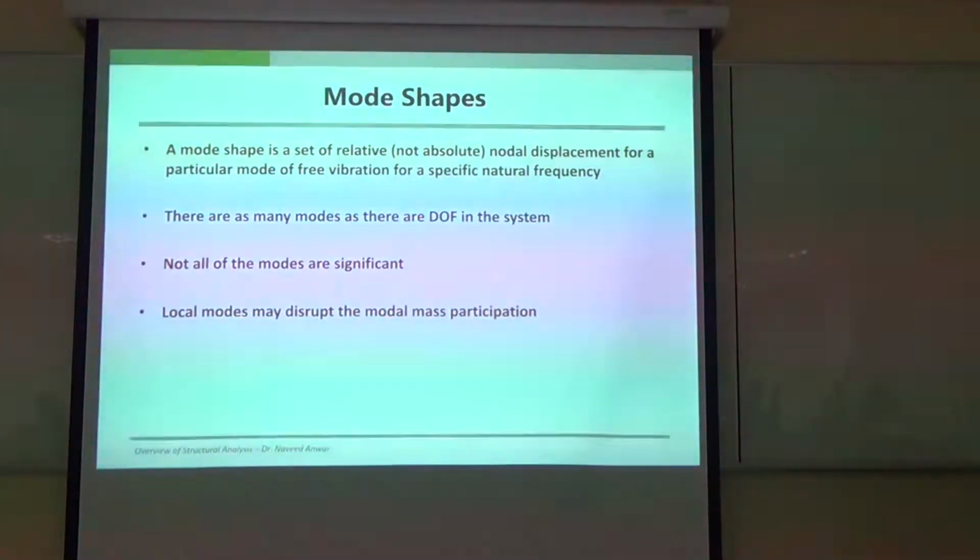So that means if you see the first mode, it is telling you that the building will deform in this way if a load is applied in that direction. So we know the weak directions. And then if you stop the building from deforming this way, it will deform this way. If you stop that, then it will deform in the third mode. So if you block each mode, it will go to the next mode.